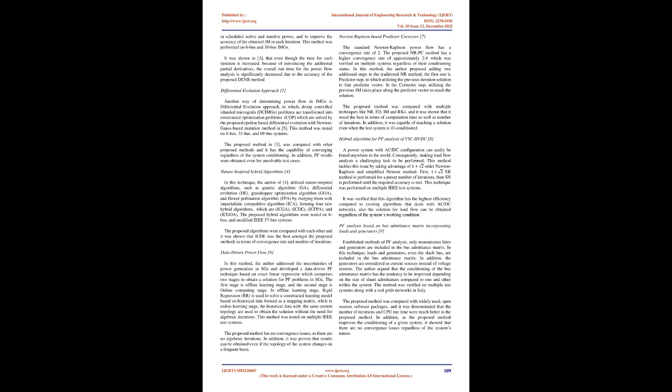Due to the absence of the slack bus in MGs, the frequency of the system is no longer maintained constant. Instead, it is considered as a variable along with active and reactive power. In this method, the existing modifications on Newton Raphson method applied for IMGs are enhanced by a droop control scheme for DGs in a system. This way, controlling injected active and reactive power by these DGs was made possible, taking into account their bus's voltages along with the system's frequency.